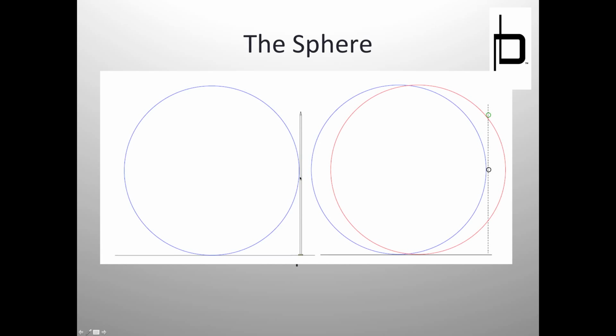If we raise the mast, in the previous picture the mast was here, at the diameter of the sphere. We've raised it. It did not stop the sphere any earlier. It stopped the sphere in the exact same place. However, if we raise the wire from here to here, we can actually reduce protection. The new protection is only under this red circle. And why is that? That's because the sphere began to roll underneath the wire. It can't roll underneath this, but it can roll underneath a wire.